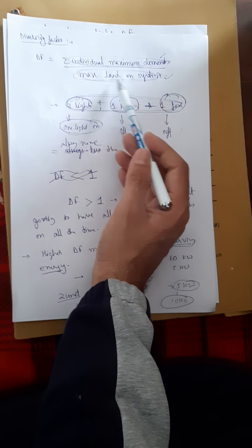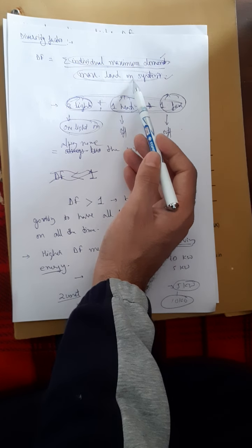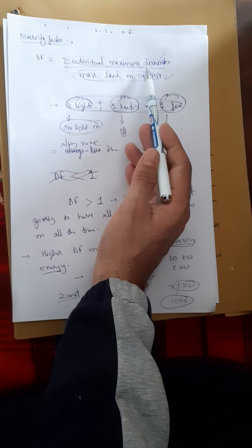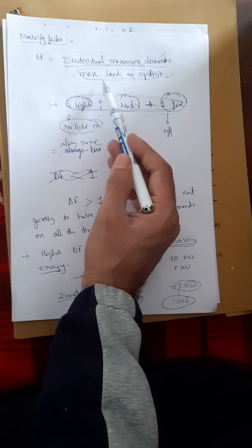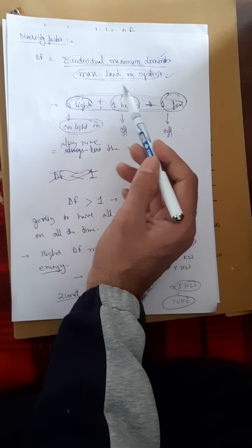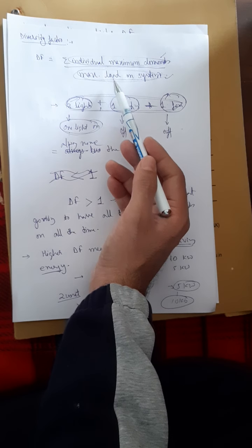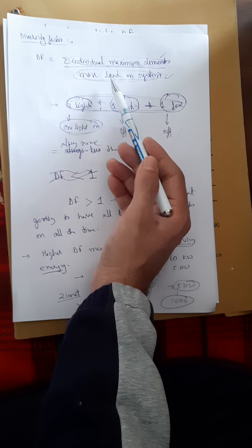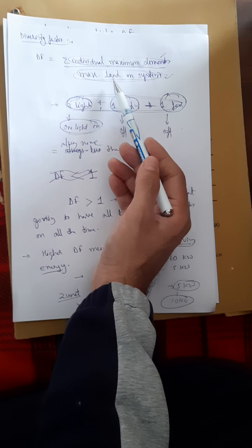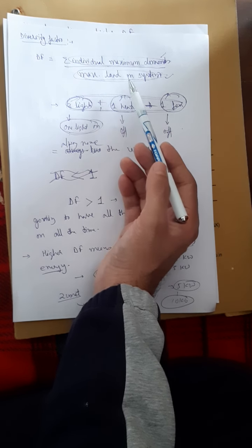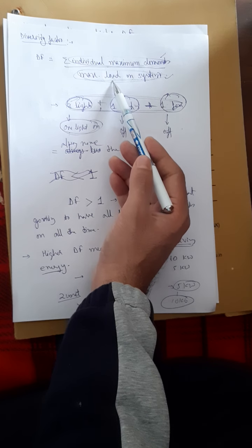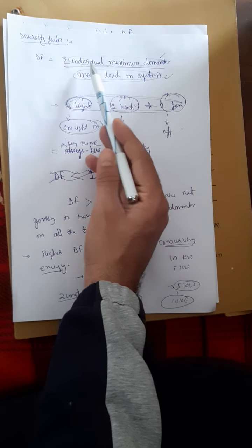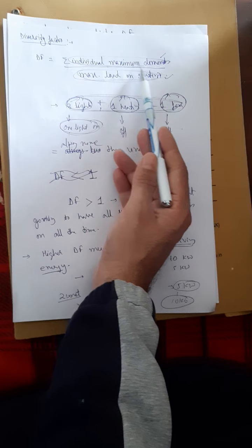This maximum demand on a system will never be equal to the sum of individual maximum demands, because we are not going to keep all the loads on all the time. Like during the daytime, we will not turn on lights. The lights are to be turned on only in the evening or during the night. So that is the maximum load on the system. It is always less than the summation of the individual maximum demands.